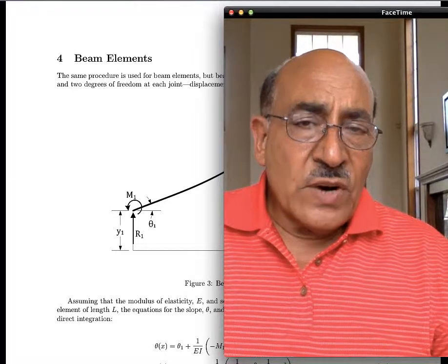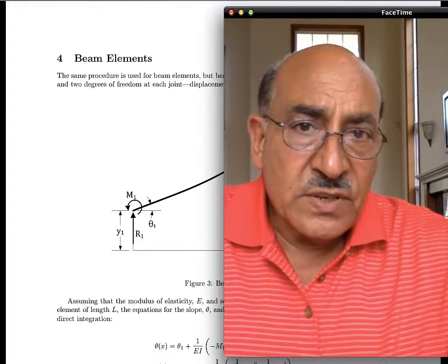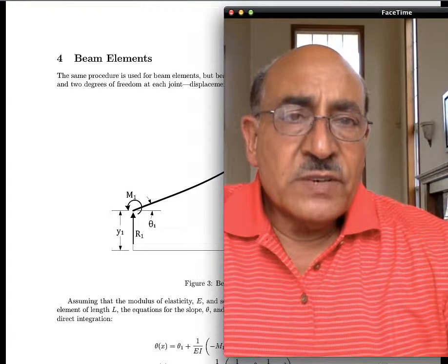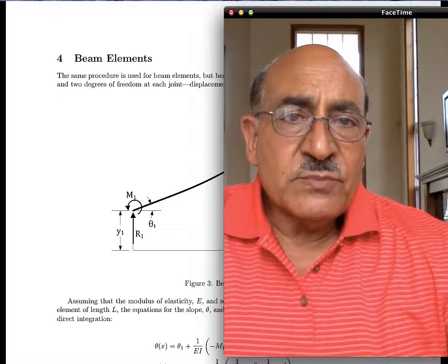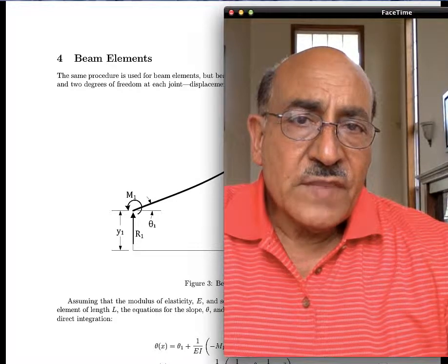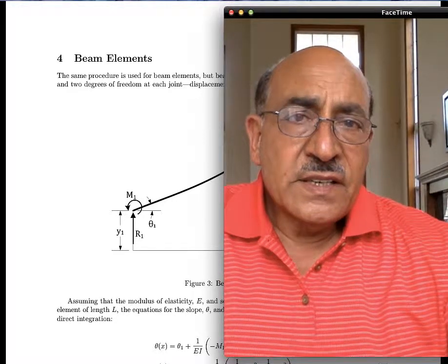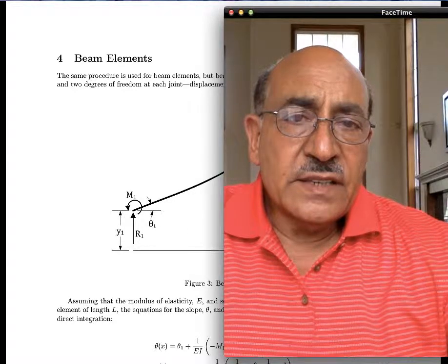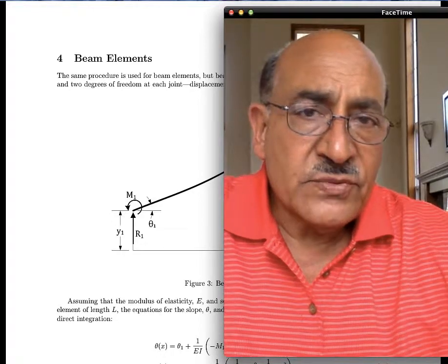So why are we doing that? Because it makes things simpler to just solve for a beam element that has assigned forces and moments alone, without anything in between. In other words, the moment is constant from left to right, and then the assigned moment, and then you have another moment coming from an assigned force.